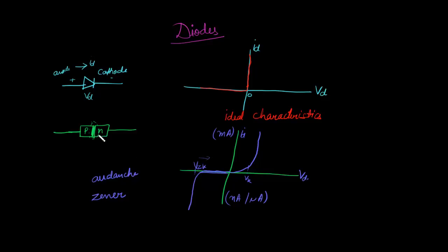That happens because of the Zener effect. As the doping is increased, the electric field increases very much in this transition region, due to which the electrons and holes are torn apart from the covalent bonds in the crystal ions, and this increases the electric current.